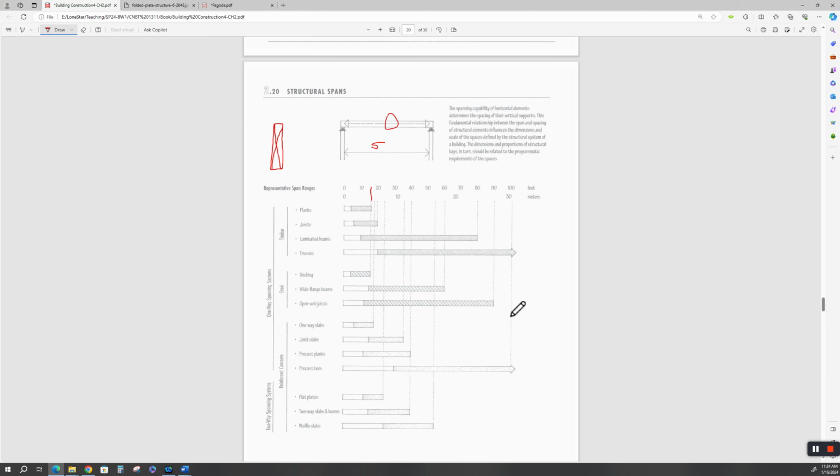I engineered some composite steel welded girders that are spanning over 100 feet for the Hardy Toll Road that you drive over every day over the Mopac yard. Because the railroad wouldn't give us a space to put columns in, I had to get outside the engineering box and go into elastic design, which was one of the first times that was ever done, and it worked just fine. I was a very nervous young engineer when we were loading the road up, but it all deflected just the way it was supposed to. It went really, really well.